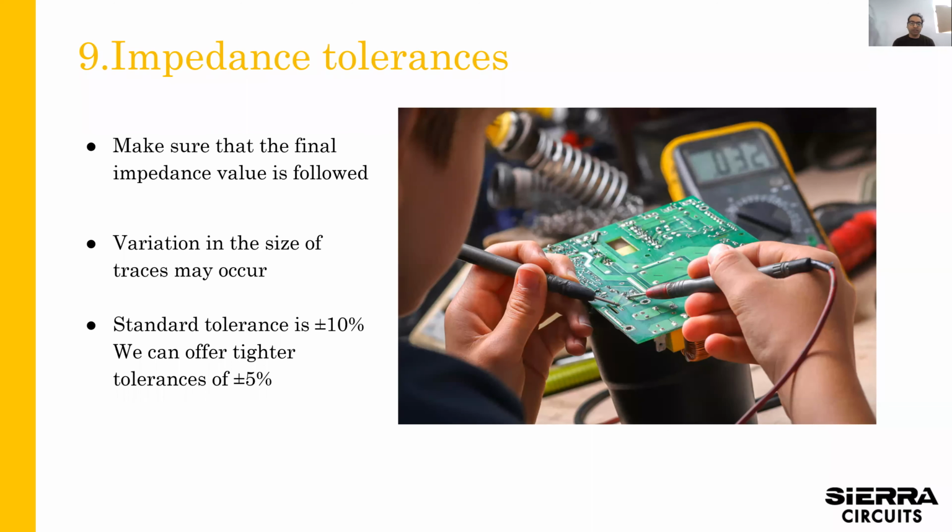which you can adjust by edge comp and thickness of the copper. Also the thickness of the dielectric material, let's say to a reference plane, which can be adjusted by picking different glass styles and prepregs, as well as understanding the temperature press cycle that you need to go through. So basically understanding press out thickness of materials and tolerances of the etched traces. Those are the key things that drive characteristic impedance.